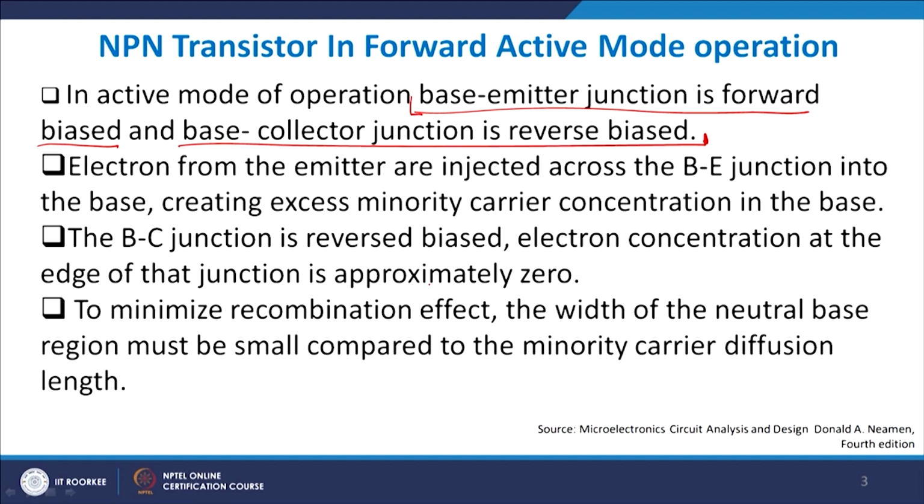Now, one important point which you should note down as far as designing of a BJT is concerned, if you remember the previous talk, is that the IS value, the saturation current value, depends upon the cross sectional area of the emitter.